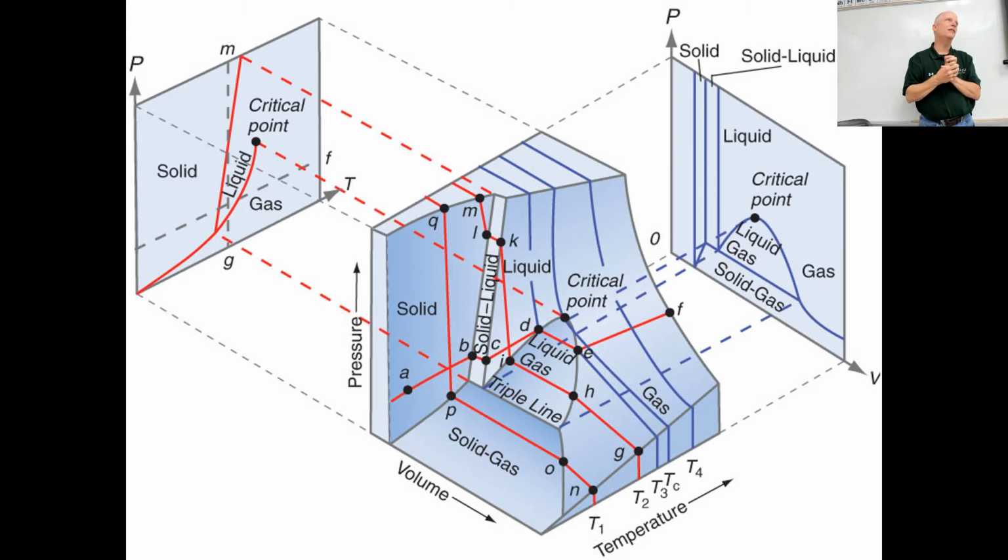He has completed wells at greater than 5,000 feet water depth. You can calculate the kind of pressures that 5,000 feet of seawater would put on your metal. And it does compress steel. It's squeezing the steel, so the dimensions change. You build it on land, and when it gets down to the subsea, the dimensions of these objects change.